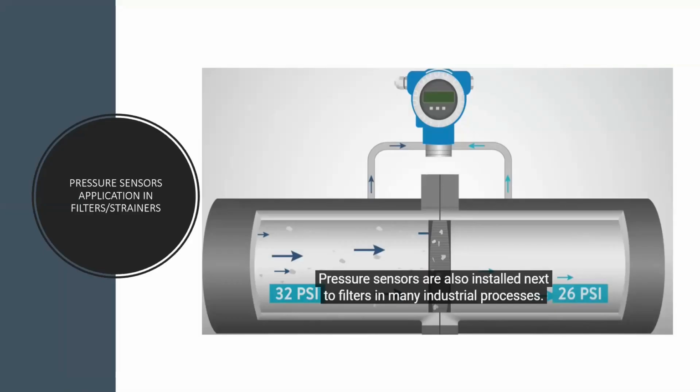So a small programming is done from the controller side, and it does these checks and transmits the information to the logic controller, where an alert will be sent to the HMI operator, so the technical personnel will know exactly the current condition of the filter.